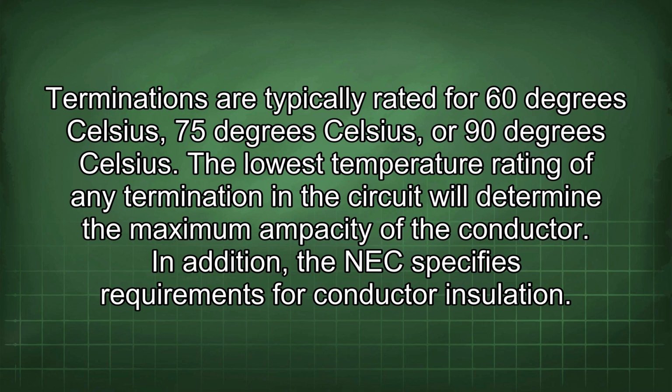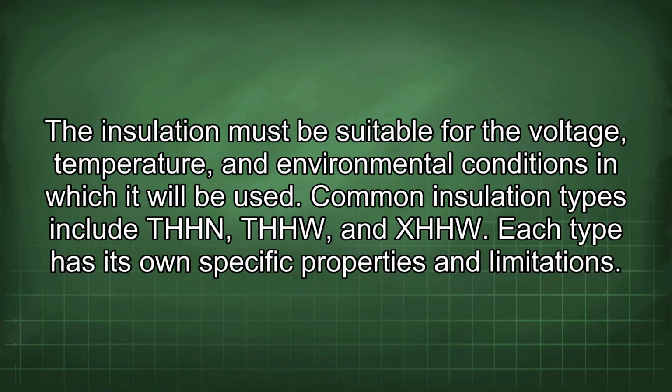The lowest temperature rating of any termination in the circuit will determine the maximum ampacity of the conductor. In addition, the NEC specifies requirements for conductor insulation. The insulation must be suitable for the voltage, temperature, and environmental conditions in which it will be used.